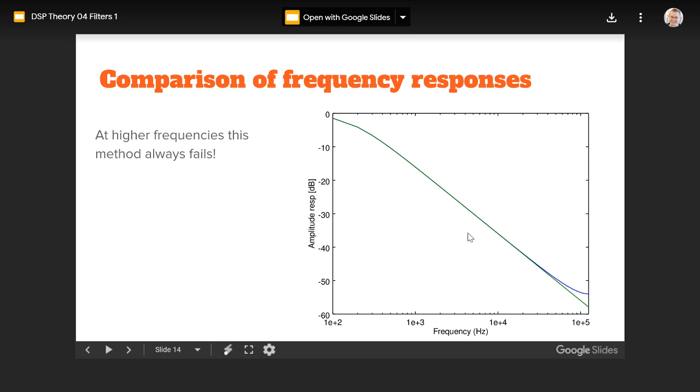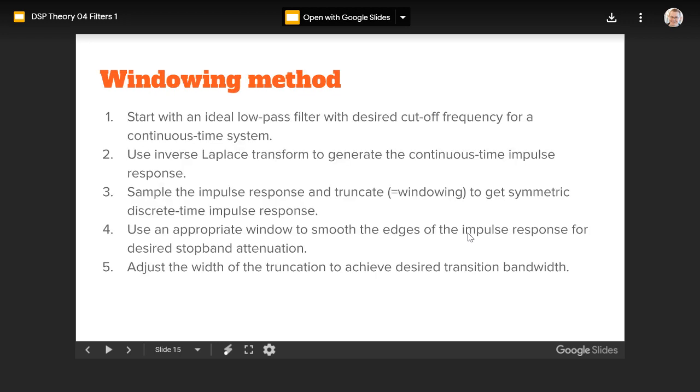Step response, sample it, differentiate it, and that's your impulse response. You have to multiply it with some constant window size, so basically it's an FIR type of system.